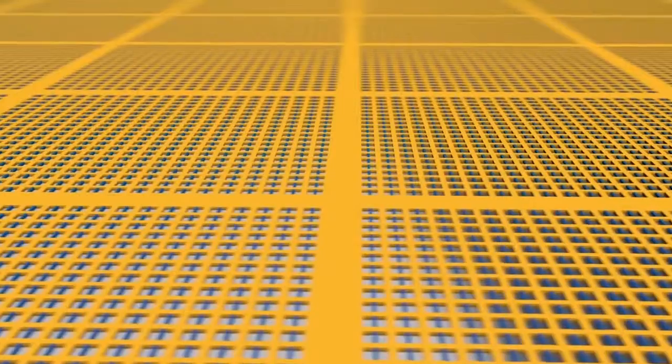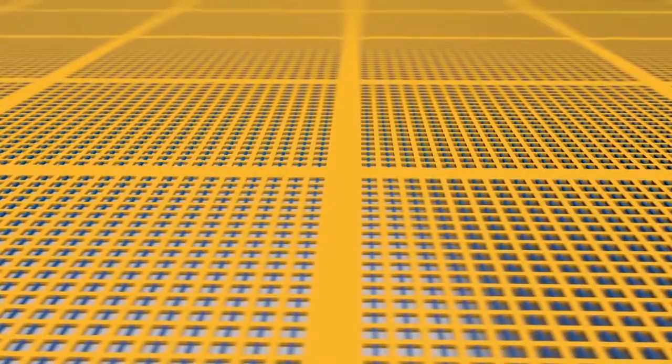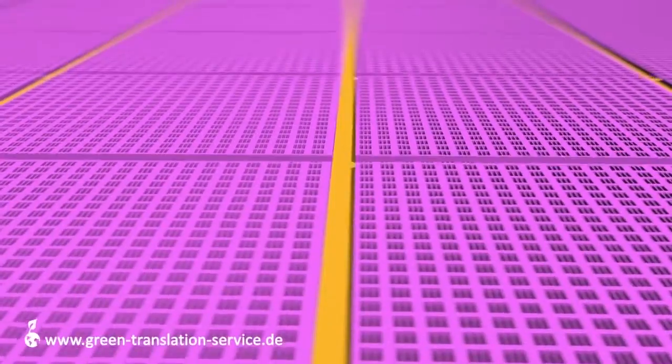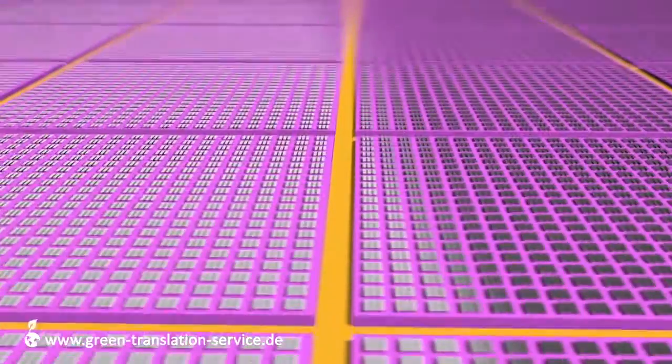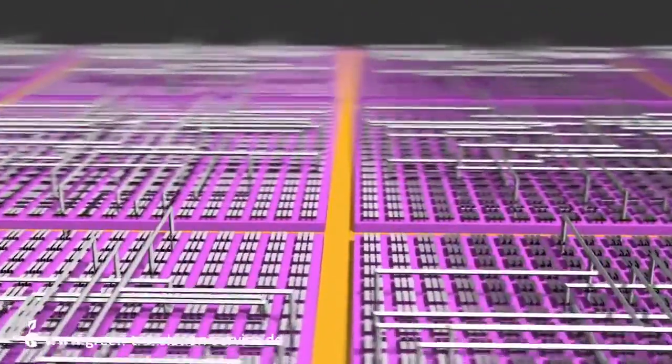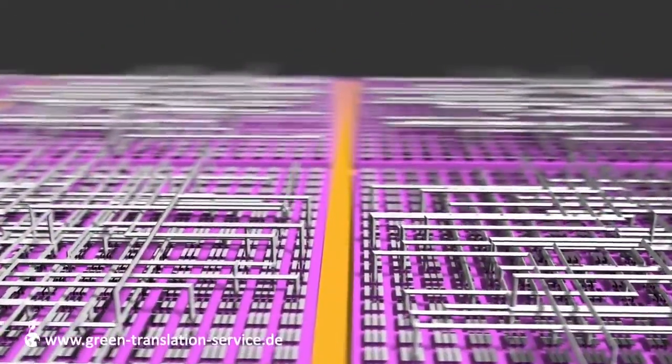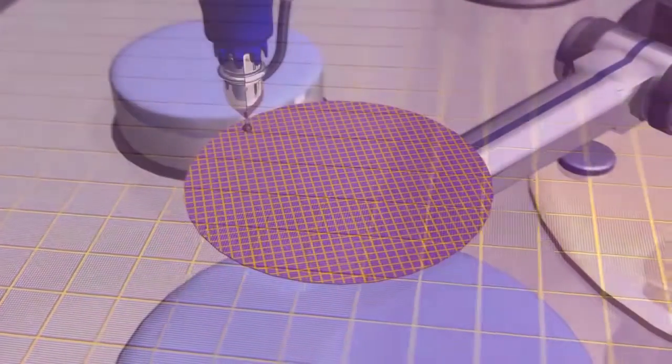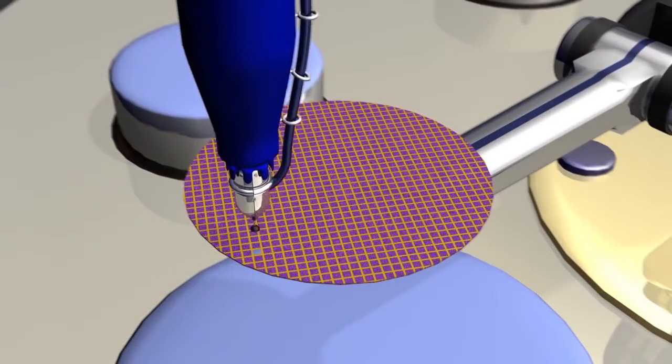The back end of line begins with the application of undoped silicate glass in which holes for connection purposes are created. These will then be filled with tungsten and the electrical connections between the transistors will be created. The end result is a wafer full of chips which will be separated from each other using a saw and then embedded in a housing.